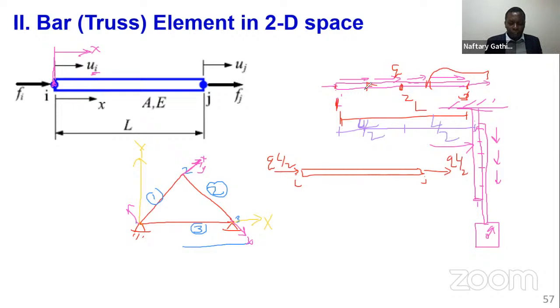Then the load that comes to this node is all this region, so it's Q times L over 2. And then this is a quarter of L, because now you have divided L over 2 by 2. So Q times L over 4 will come to this node. I hope it should be clear and simple so far. That's just a point I found necessary, so that in case you come across such a loading, you're able to resolve it and proceed with your analysis.